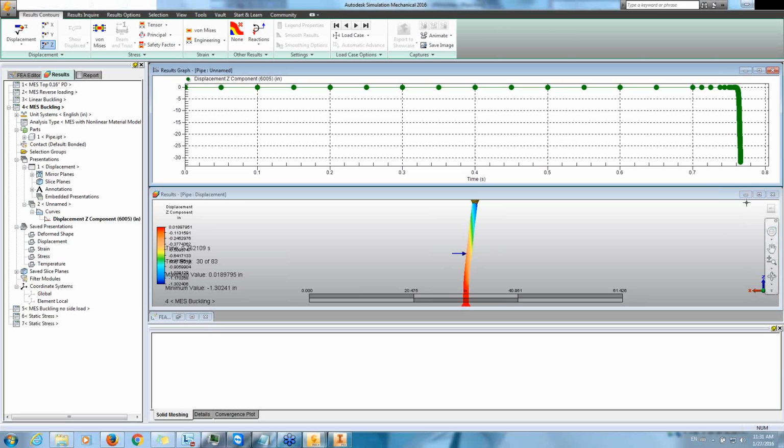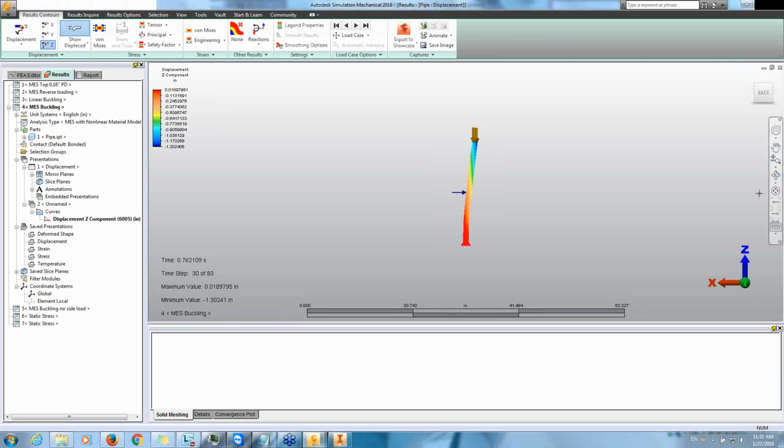Just due to its geometry, certain geometries you would need to apply that load, otherwise you won't attain that buckling state. In other situations, what could happen in real life is you have a structure, and it gets loaded in a certain way that produces some kind of a permanent deformation, which will cause it now to have that geometric imperfection that's going to cause it to buckle.